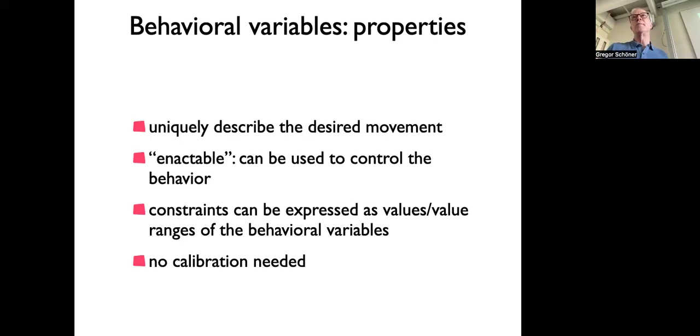So the motors on the robot would actually be servo motors. That is, motors that have their own sensing, sometimes called shaft encoders. So they sense how much the motor has actually turned and make sure that it really turns as desired, right? So there is a control that really deals now with physical disturbances.